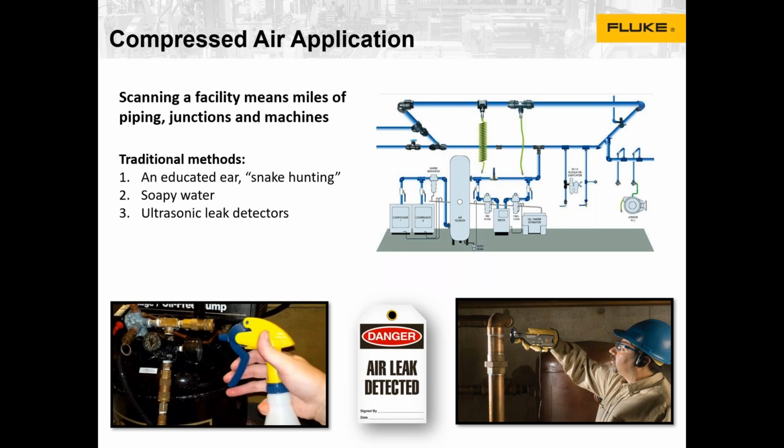And then the other thing that our customers were doing was using ultrasonic leak detectors. You've got the picture in the bottom right-hand corner. That's probably something similar to what you all have seen, a device that's listening for ultrasounds or sonic sound waves, and you've got the headphones. So you're listening for something very specific, and somebody that's trained on the technology and how to use it, as well as has a considerable amount of in-field training or field knowledge, would go and inspect areas, again, able to identify leaks.